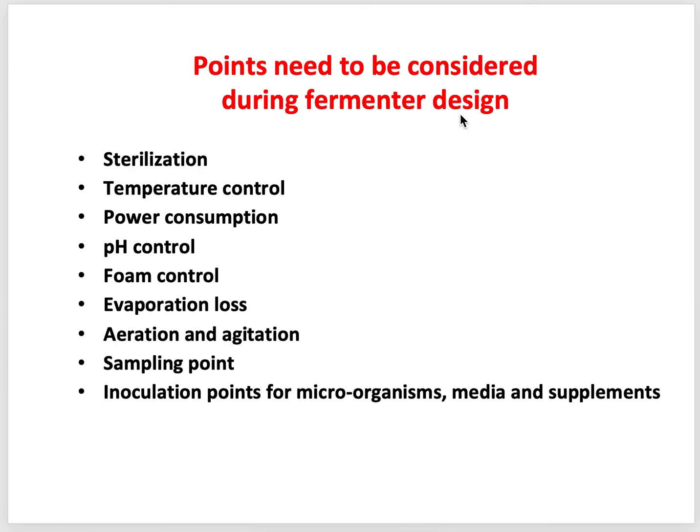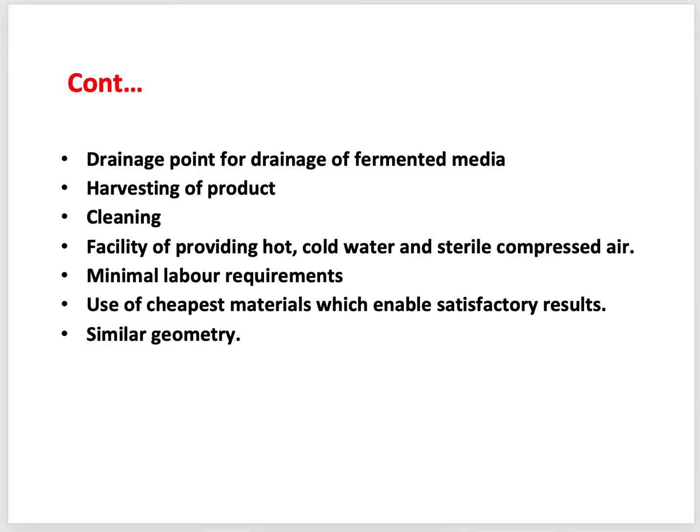But in case of continuous fermentation, as I just said, we have to continuously add fresh media, microorganisms, supplements. So that's why there should be an input point there to add these things. Then a drainage point for drainage of fermented media, harvesting of product, cleaning, facility of providing hot and cold water and sterile compressed air, minimal labor requirements, use of cheapest materials which enable satisfactory results,